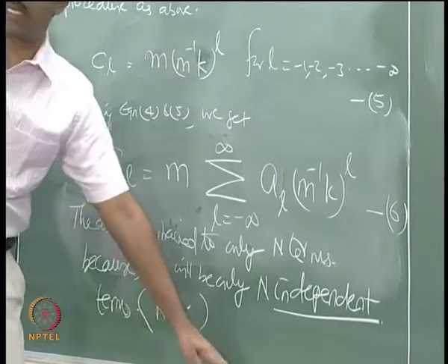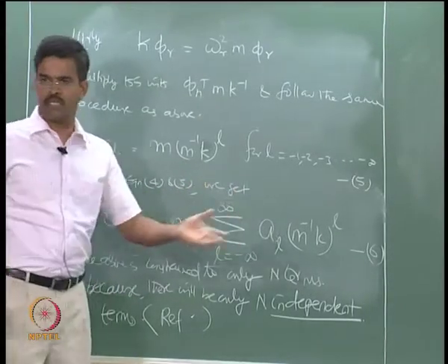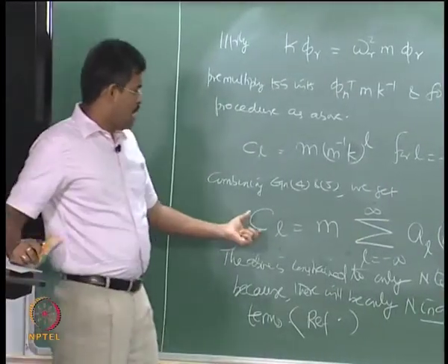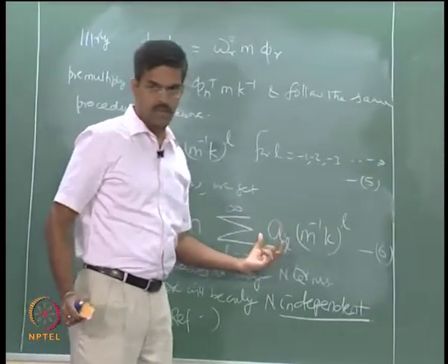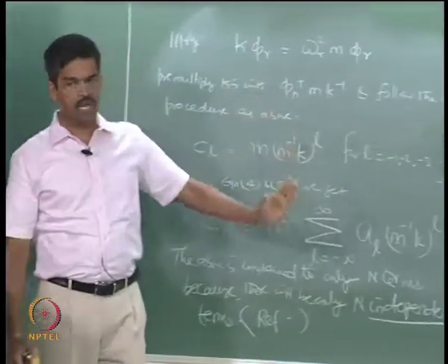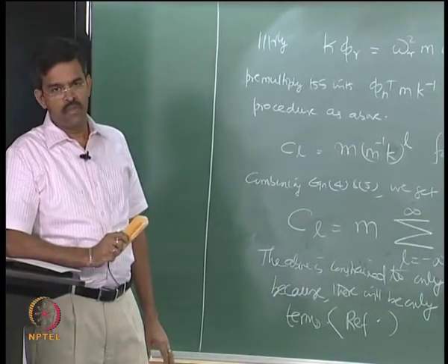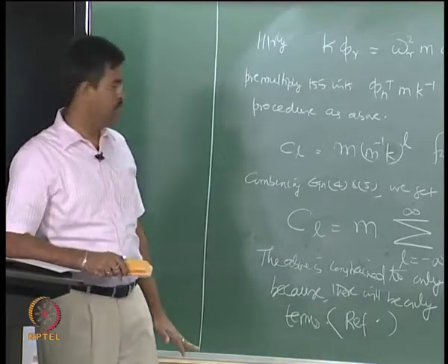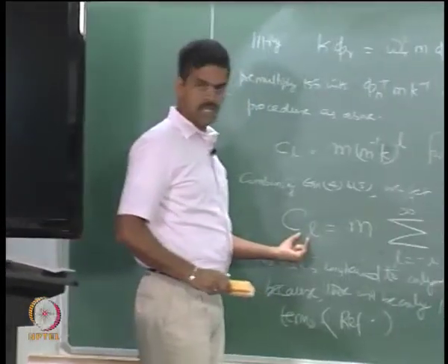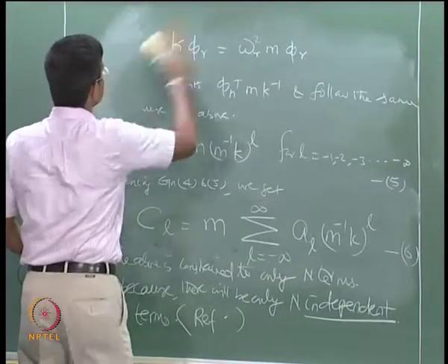So, I rewrite this equation again, instead of minus infinity to plus infinity. Have you understood? Caughey model is including all the frequency ranges in my whole system, where Rayleigh was not doing it. Okay? That is the difference now, that is the deviation of this model from the Rayleigh damping. So, I rewrite this equation 6 with finite terms like this.